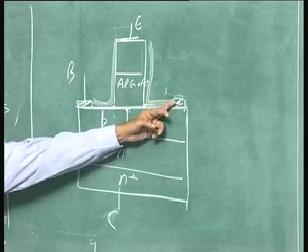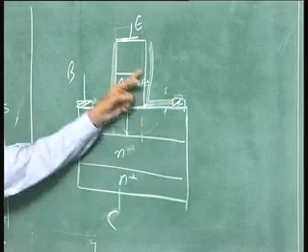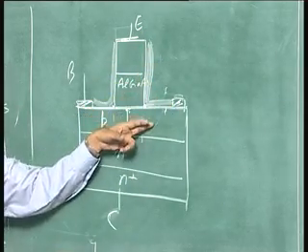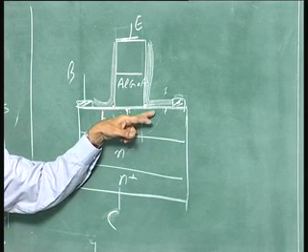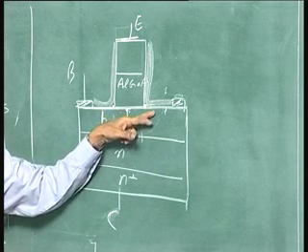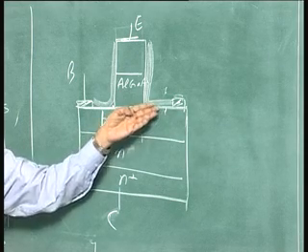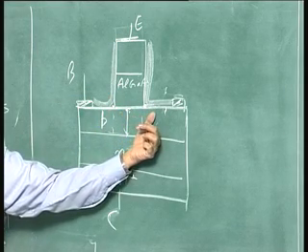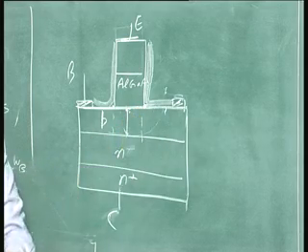If it is coming here, you have to remove it by lithography. So, I am showing it here. This is a passivation layer which protects the junction, which protects the surface. So, you can't put a deposited oxide here. When I say you can't, it is possible for you to deposit, but it will not serve the purpose, because that SiO2, any oxygen containing layer, will react with gallium arsenide to release arsenic from the gallium arsenide.